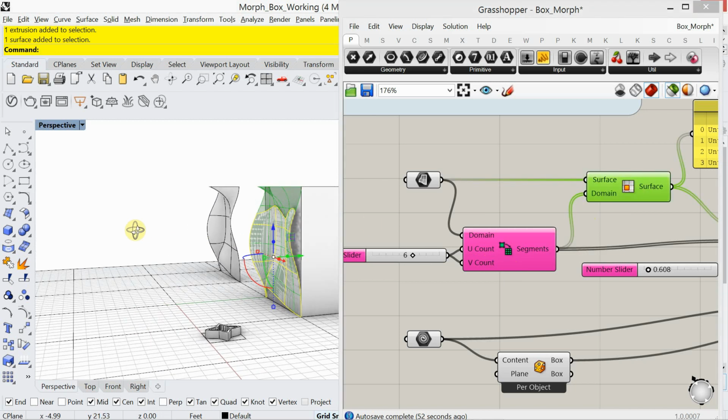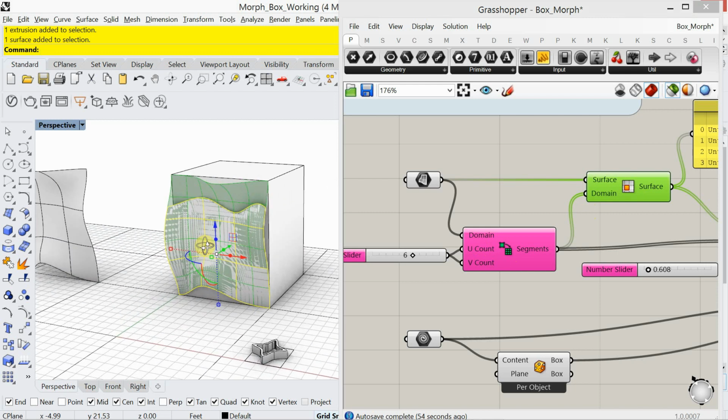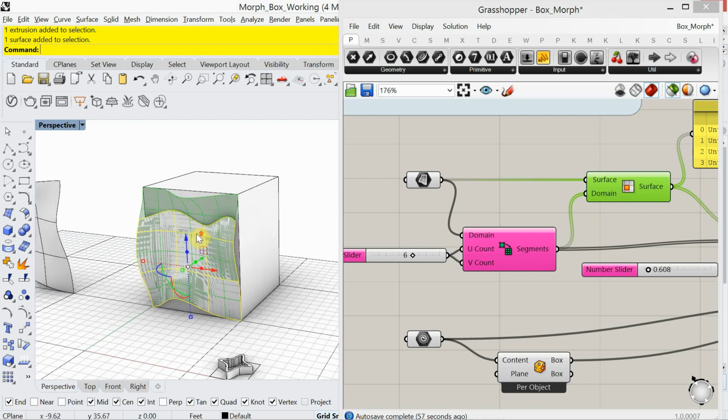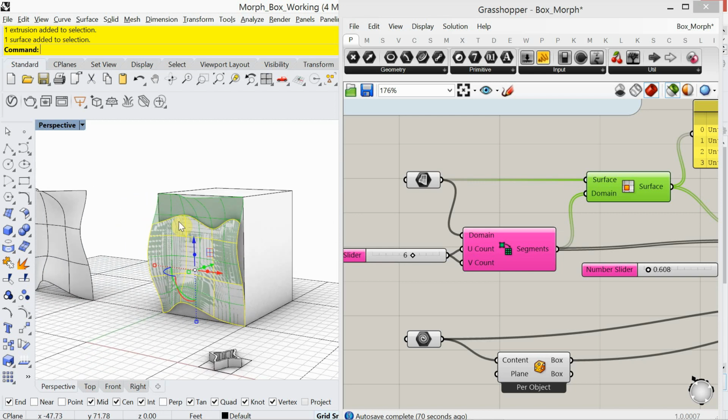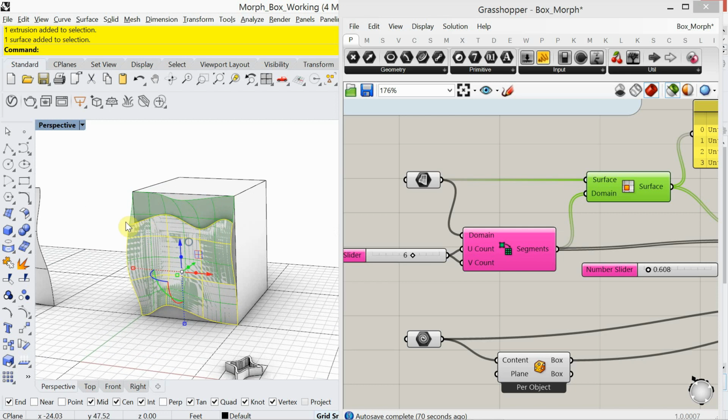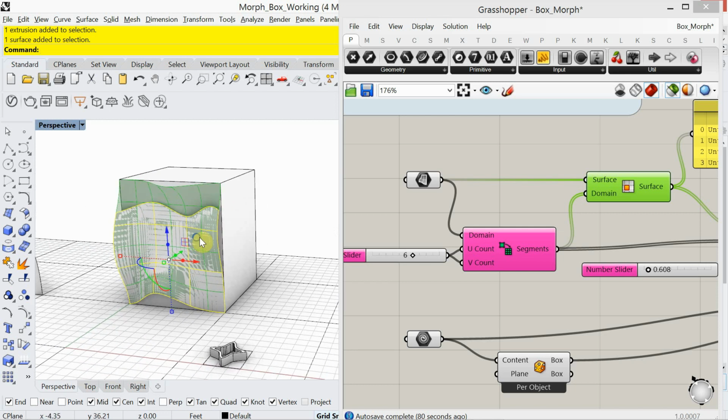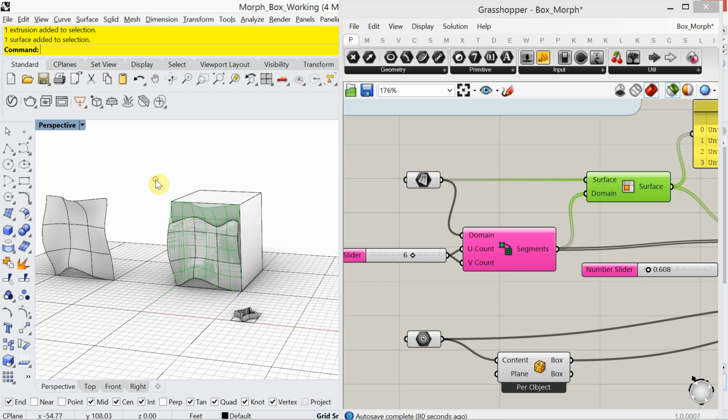It just ignores it. So I remember, way back when I was first introducing this concept to students, this box morph, that was the first thing students would run into is, it's not working on my surfaces. It's not working. It's extending them beyond and making a box out of them or a full rectangle, and that's the issue there. So it doesn't work on trimmed surfaces. There's other ways to make a surface like the one we made, but by trimming it, it's just not going to work.